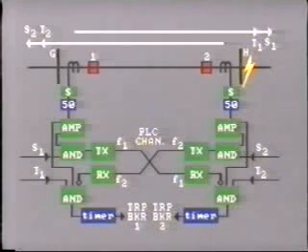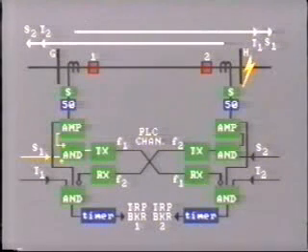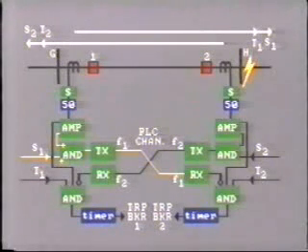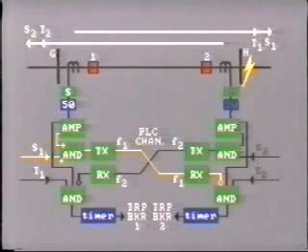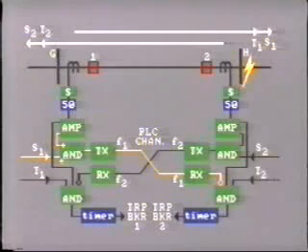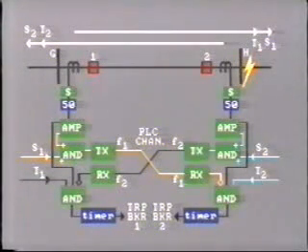This fault is detected by both trip relays at station G. The starter relay starts the transmitter to send the half-cycle square wave signal along to the receiver and tripping logic at station H. The overcurrent relays at station H operate as non-directional. This starts the transmitter, and at the same time it sends a tripping signal into the logic circuit, attempting to trip breaker 2.